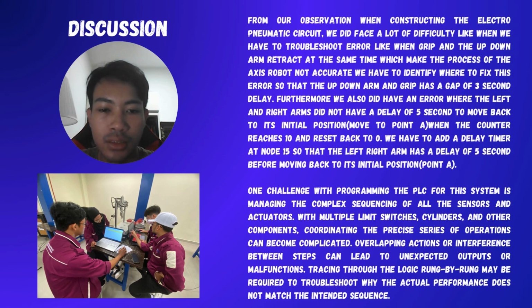When the counter reached 10 and reset back to 0, we had to add a delay timer at node 15 so that the left-right arm has a delay of 5 seconds for moving back to its initial position, which is point A.